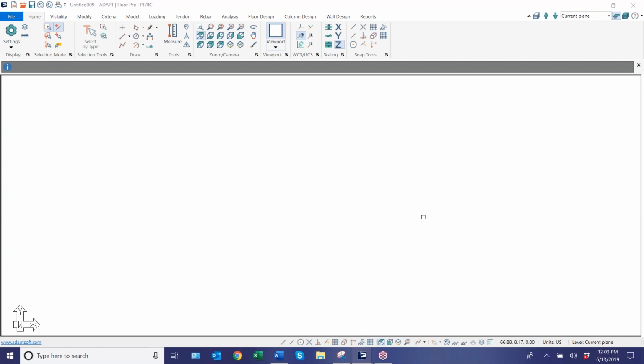So the purpose of the design strip is to generate design cuts that allow you to process information relative to the slab or the beam, and then the program passes that design cut or design section data to a processor called Designer. It's an executable that's embedded inside Builder, and that designs those sections for reinforcement, for stresses, and so on.